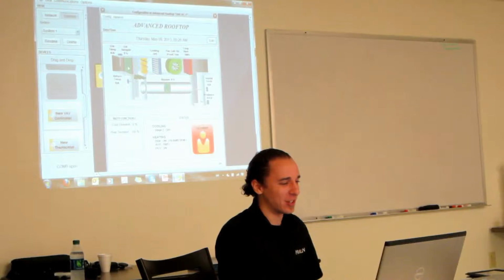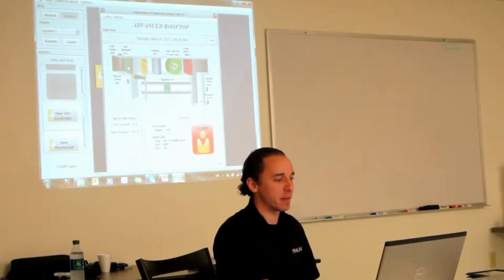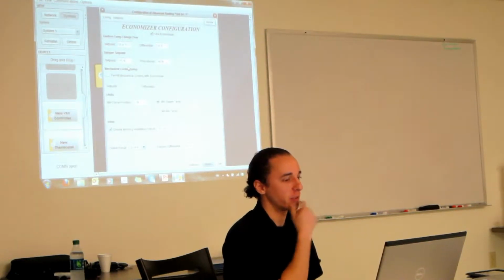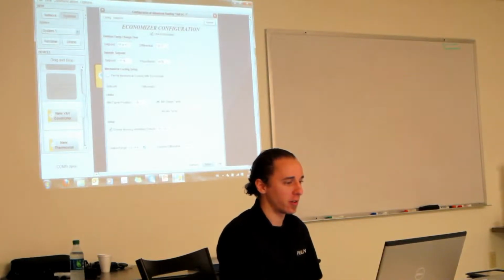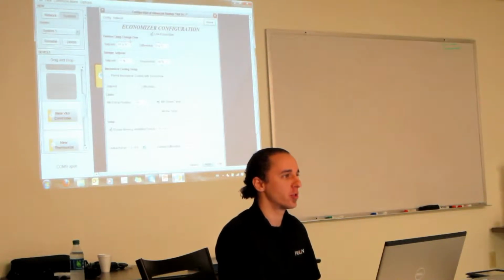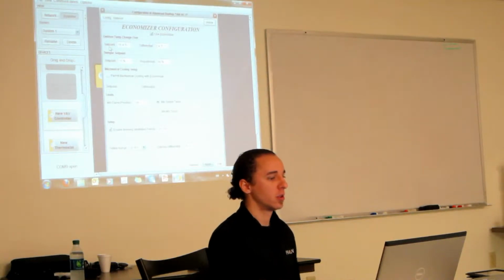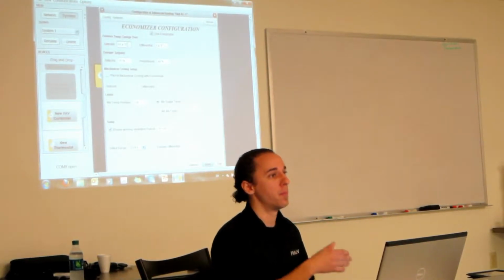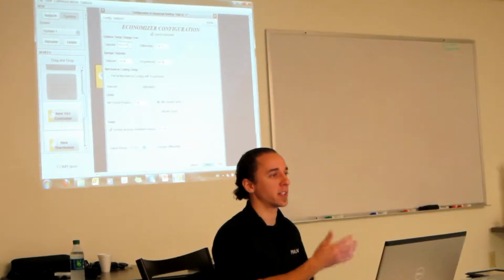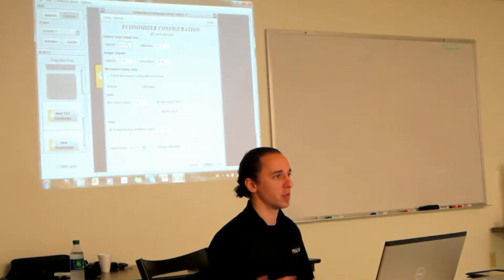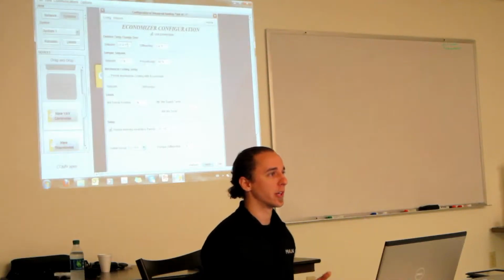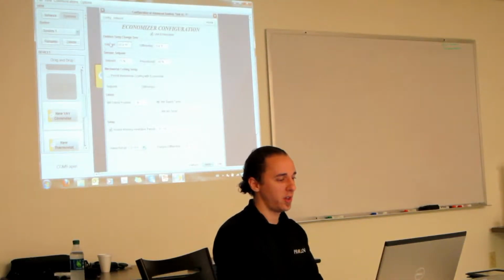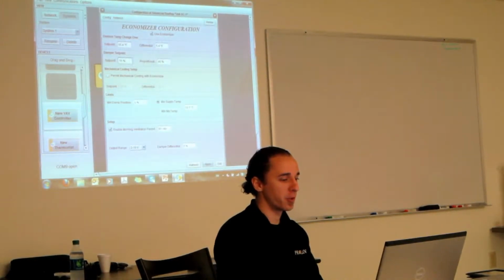Very good job. So if I double click on my fresh air damper, it brings me to my economizer function. So here's our set point, our outdoor temperature changeover. So basically, we're only going to enable our economizer function if it gets like this or cooler. So high lockout. Exactly. So if it gets warmer than that, well then there's no point in using hot air to try to cool down your system, right? So here you can change the value. Here's our damper set point.